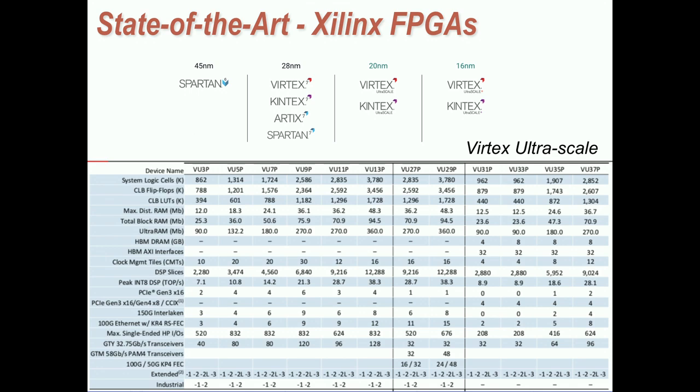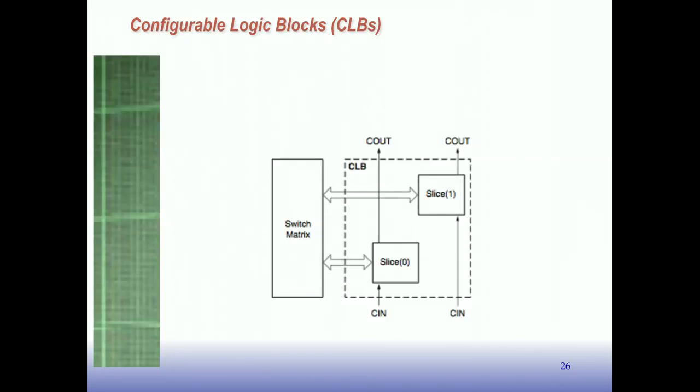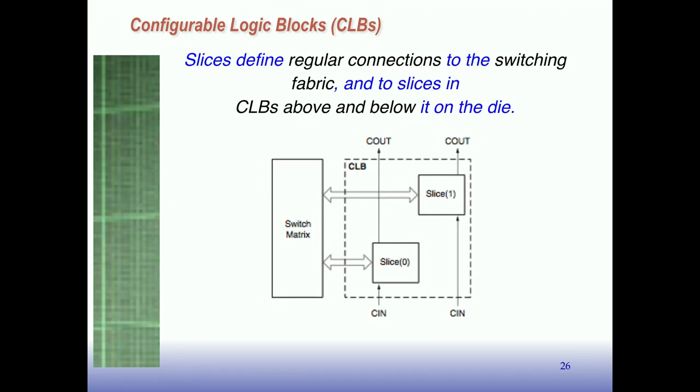So I'm going to show you some more details of commercial FPGAs. This is the way that on the Xilinx FPGA, or most Xilinx FPGAs, the organization is. The CLB is actually decomposed into 2 slices. I'll show you what's inside a slice. And then these are the connections out to the switching, the configurable wiring. And then there's usually connections up to neighboring CLBs, so some direct connections.